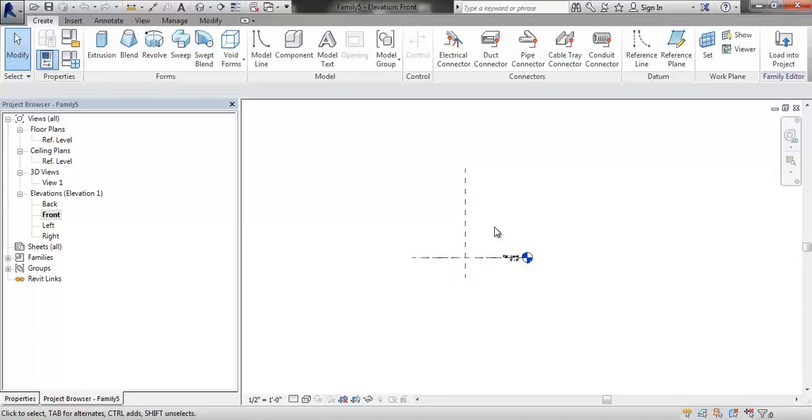All I need to control at this point, now I'll need to think, right? Because I'm embedding logic into a new family. So if I went to do an array with this family, and I just did the array function, I would still have to open up the last family and control parameters. So even though we're not controlling anything in this family, I still want to path those parameters so I can grab them in the next hierarchy of family, right? So the first thing I'll do is load in my blade.